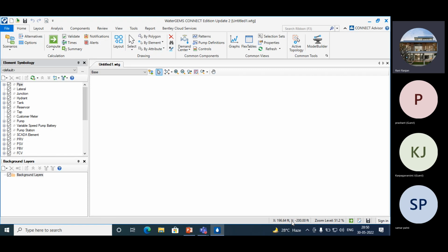And at this side, it will show you the X and Y axis distance, like coordinate, UCS, user coordinate system. It will display where you are going to create. See, it will move according to our mouse. Dimensions will move according to our cursor. See, X and Y axis. Because we are going to work in 2D, that's why it will show us only two axes there, X and Y axis, user coordinate system.